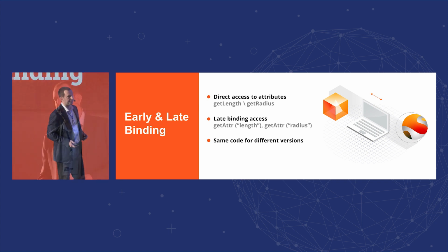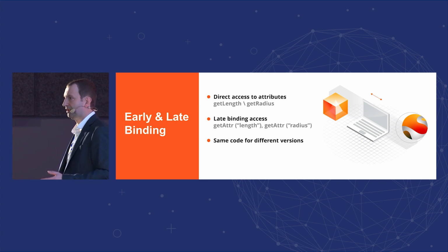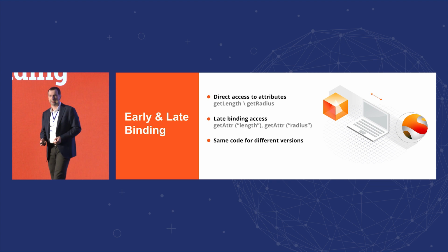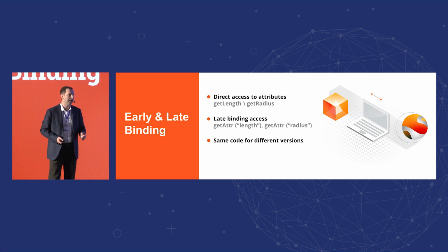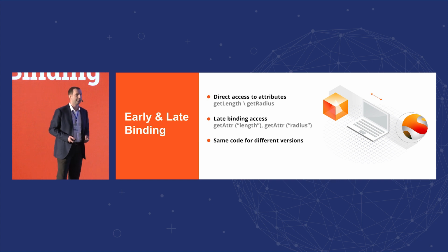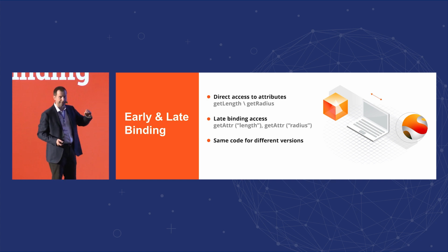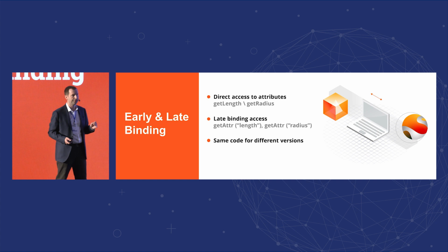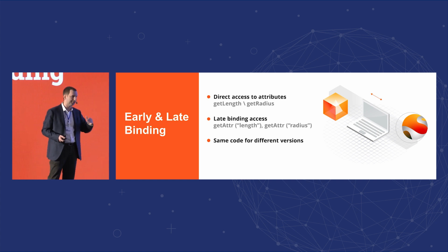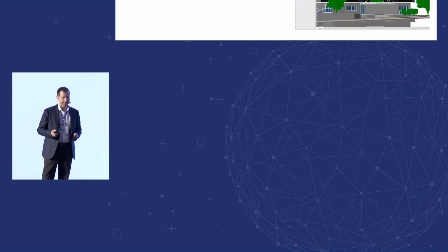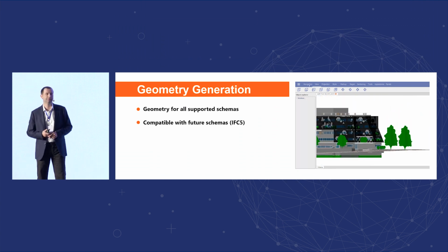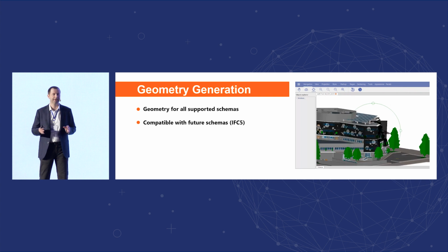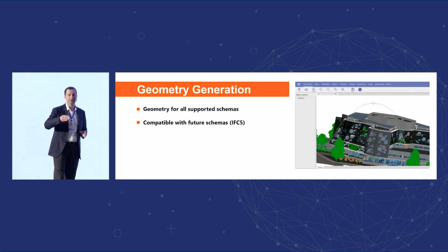The next level we implemented is the late binding API. It's a higher level, and it allows working with different formats in a common manner. This level of API is also used further in geometry generation, so we are working in a similar way with both formats. It needs to be taken into account that, unlike many other formats, IFC has implicit geometry inside.